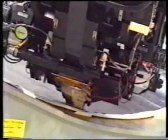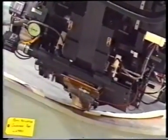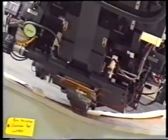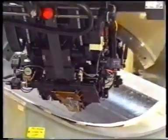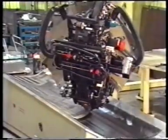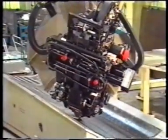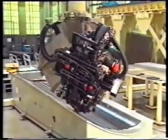The head deposits rows of tape, butting each row against the edge of the previous one. At the end of each row, the head cuts the tape and moves into position to deposit the next row. There is essentially no limit to the size of workpieces that can be tape rolled, but the shape of the workpiece has to be relatively flat to butt each successive row without gaps, overlaps, or wrinkles.